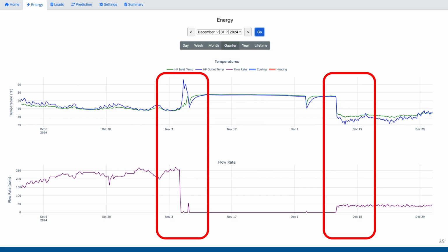Maybe the person paying the energy bills, when the natural gas bill comes in the mail, they would have gone wide-eyed, but it's oftentimes things like this that aren't caught and sort of accumulate issues. Thankfully we were able to get the controls contractor to go back to site and turn back on the ground heat exchanger system to do the majority of the heating. But again, that would have gone unnoticed all winter, and then they would have had issues in the summertime.